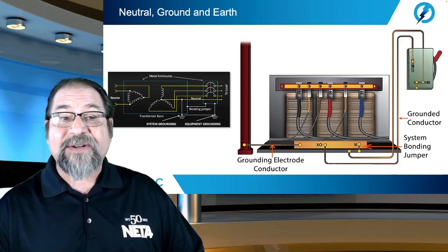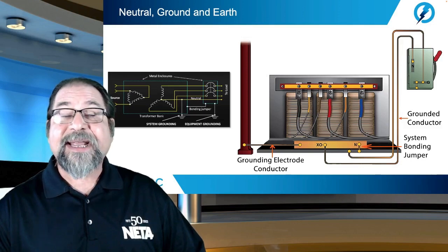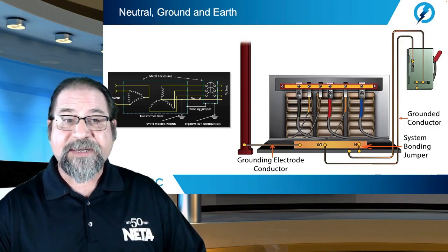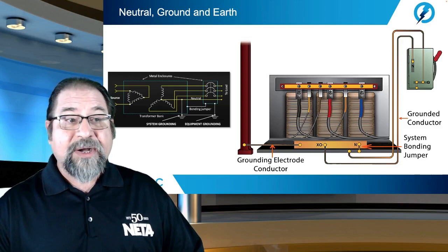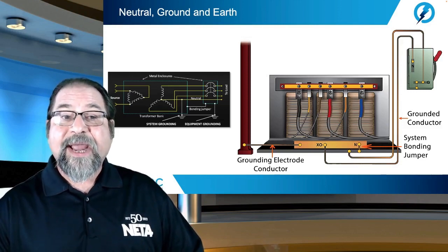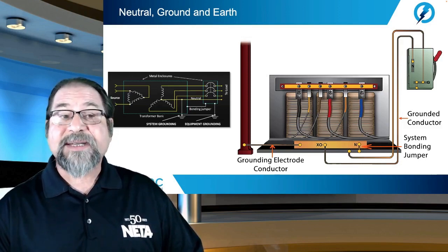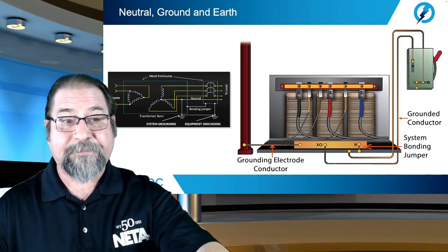So, the installation of grounded conductors and neutral conductors is carefully defined in electrical regulations. Where a neutral conductor is used also to connect equipment enclosures to earth, care must be taken that the neutral conductor never rises to a high voltage with respect to local ground.